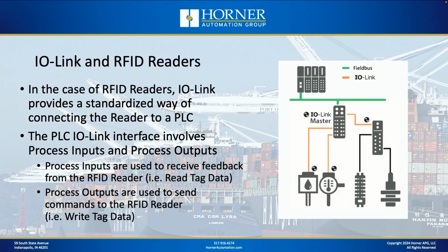So when we're talking about IO-Link and RFID readers, one of the characteristics that we're taking advantage of is the fact that IO-Link offers a standardized interface for interfacing smart devices like the RFID reader with the PLC. And that interface looks like, effectively, 16 words of process inputs and 16 words of process outputs. And all the work really in the application is done through that particular interface.